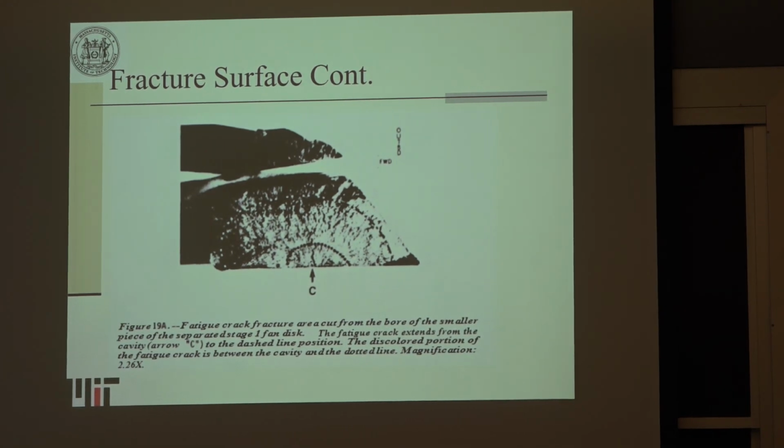Couple of these that I'll pass out. What you would do is take a metallurgical mount, look at it under an optical microscope, and lay it down in such a way that you can look at the surface. What you're seeing in these two that I'm going to hand out is one is a weld with some lack of penetration in the weld, and the markings on the various sections are micro hardness markings.